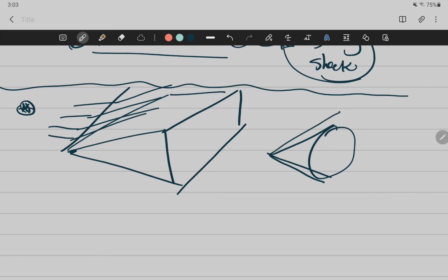The shock waves themselves are going to look similar to the two-dimensional shock wave. And you're right, you're going to get a shock shell around the cone. But what's going to happen to the streamlines is that they are not going to be parallel after the shock wave like these ones were, because of the waves that we are going to experience in this other direction that we didn't have before, right?